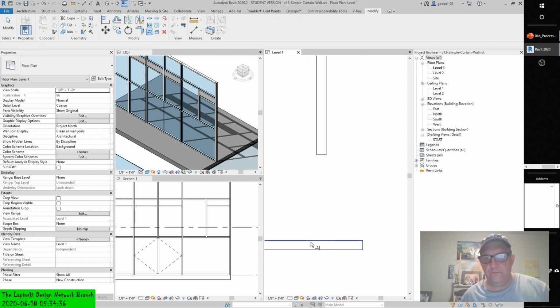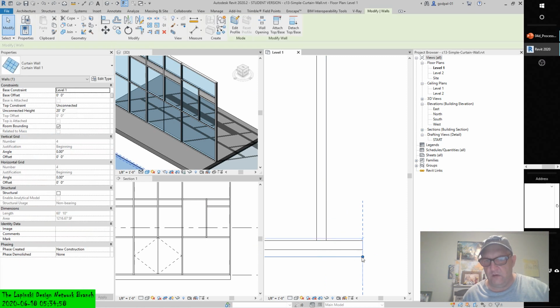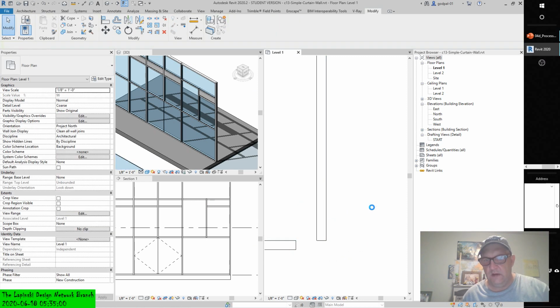And you can tab through each element. And there, that's a little better. So it can be a little goofy. You gotta get to the face that you want. And you'll see it'll extend or trim based on the face you select or the tangent line. So if we, again, select the reference line as the extent boundary.